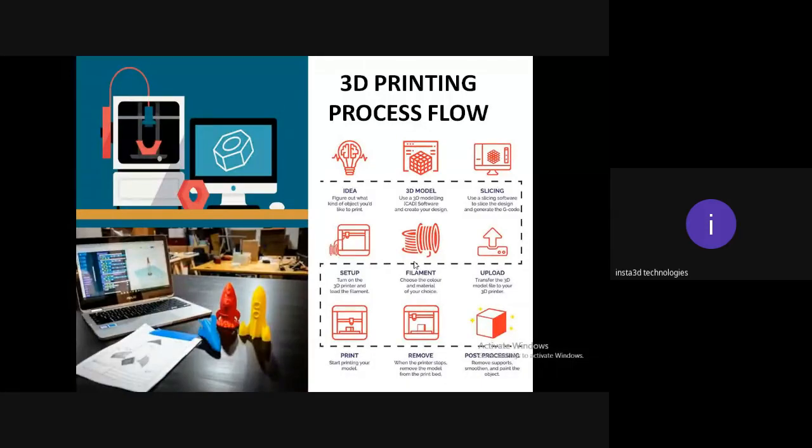You can design in any of the softwares, and you can convert that design into a 3D printable file. That process is called slicing. Using a slicing software, you can generate G code and M code, which is a language for a 3D printer. After slicing, the designed model is sliced into thin layers, similar to slicing fruits or vegetables.